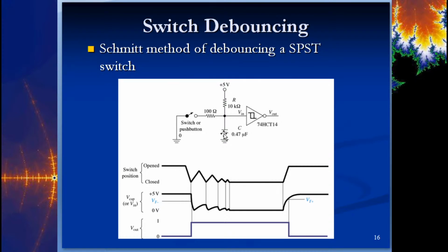But when that switch gets punched or when it gets turned on, it's going to bounce a little bit. But because you have this capacitor here that is getting these small charges and discharges, that's going to smooth out those transitions. It's almost like a shark fin, right? So instead of getting the full jump up here, it has to charge. It can't just charge automatically. So it takes a little bit of time to do that. So we actually use that to our advantage, and this will debounce that switch, and then you have a nice crisp output as a result.